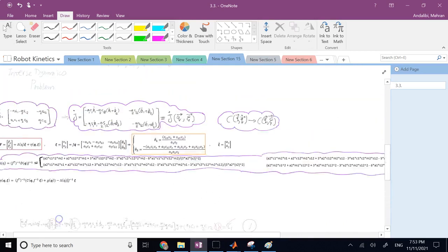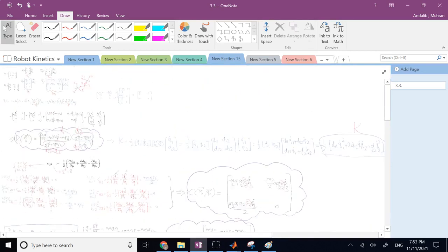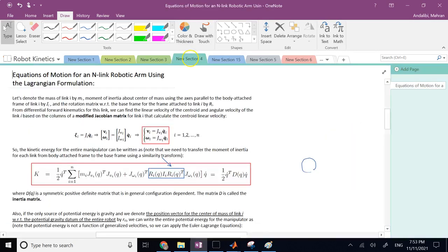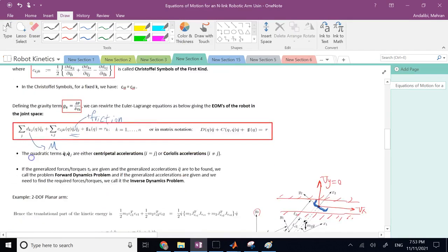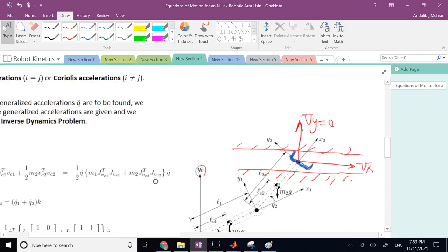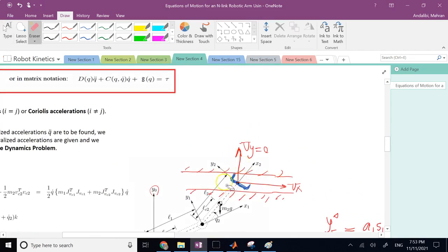And now, just out of curiosity, you might say, if I find lambda, what is lambda really going to be? And the answer is, it is going to be your constraint force. If you have your end effector stay only along this horizontal guide, because the motion is horizontal along this guide, there will be some force applied in this direction, some constraint force F. That will force your end effector not to leave the guide.